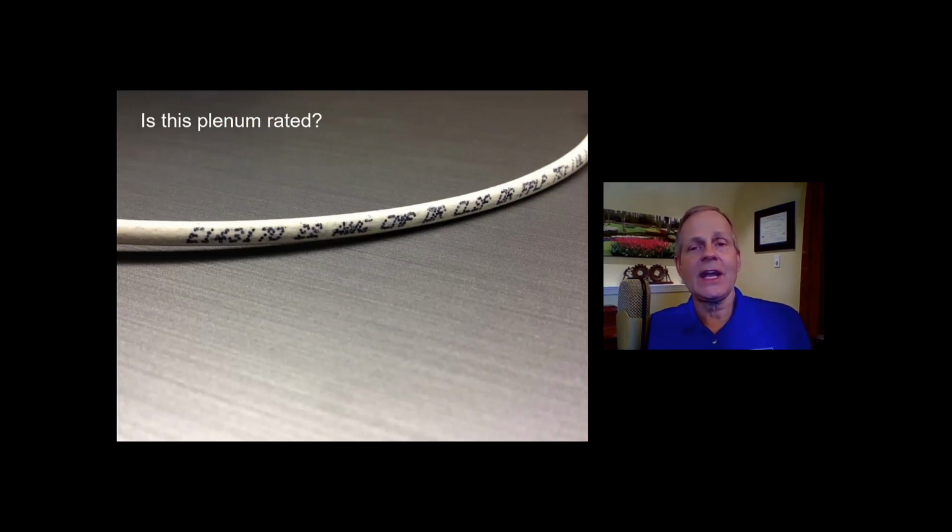All right, so let's take a look at this particular cable. Look at the letters and the numbers, see if you can determine if this is plenum rated. So remember, we're looking for a letter P as in Paul somewhere in that lettering string. Okay, so if you said yes, that it was plenum rated cable, you would be correct. You can see here it's labeled CMP, that P is a little bit distorted, but it is in fact the letter P. So this would be an example of plenum rated cable.